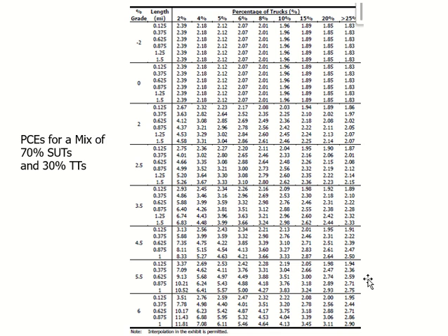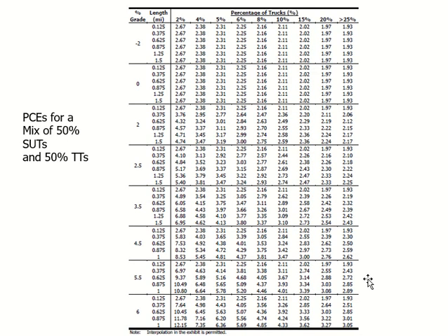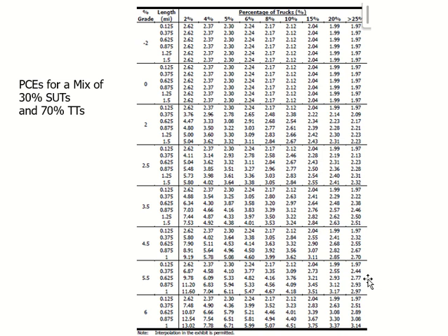To use this table, I must know three things: the gradient, the length of the gradient, and the percentage of heavy vehicles. They call it percentage of trucks, but trucks means heavy vehicles. Even if it's a bus, a big bus, small bus, whatever, it's part of this percentage. Clear? If single unit trucks and trailer trucks are equal, then we use this table. Again, we need the same thing. If single unit trucks are less, trailer trucks are more, we use this table. Clear?